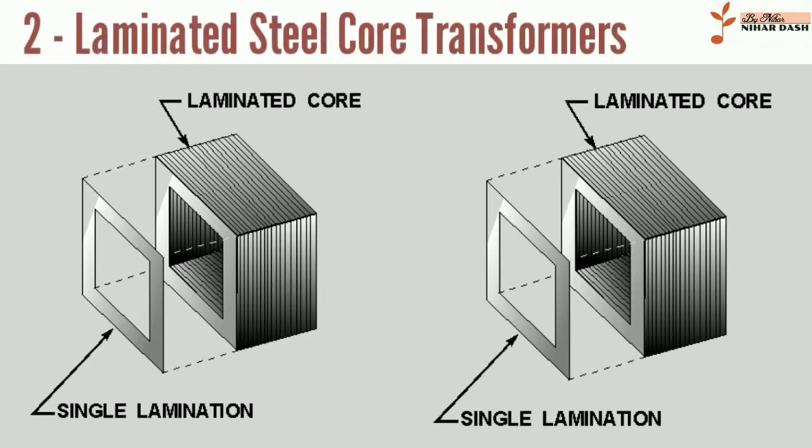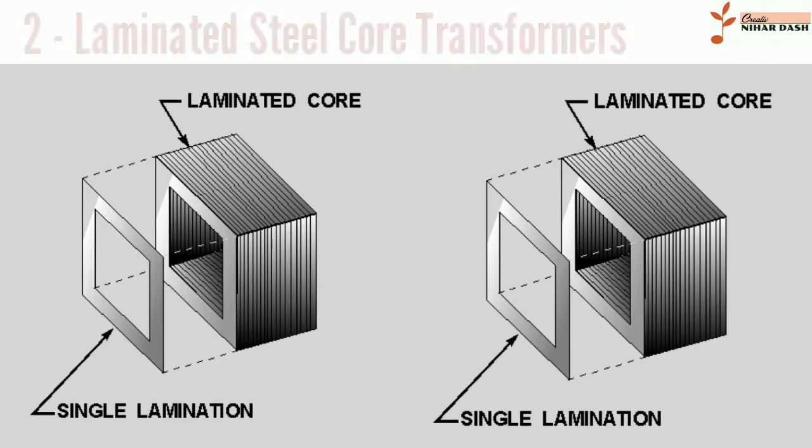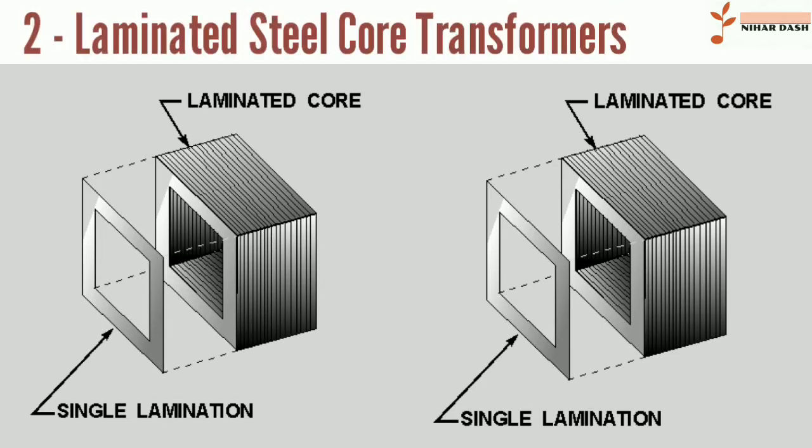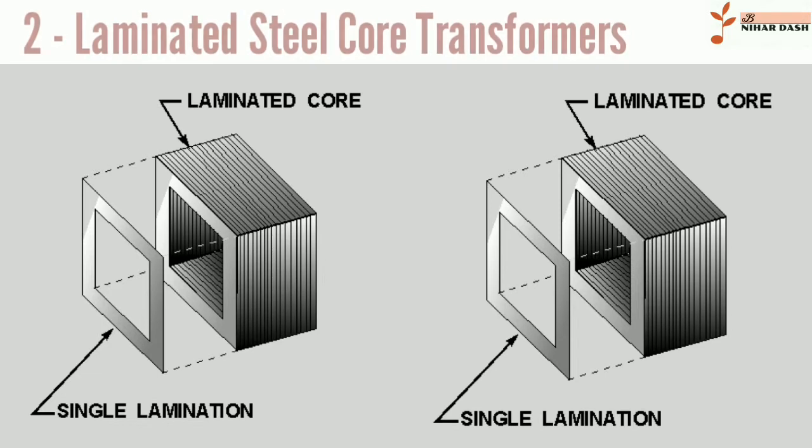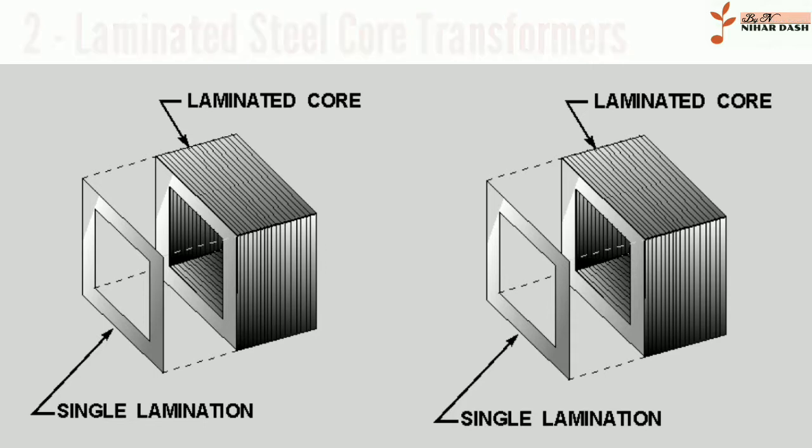One common design of laminated core is made from interleaved stacks of E-shaped steel sheets capped with I-shaped pieces, leading to its name of EI transformer. Such a design tends to exhibit more losses, but is very economical to manufacture. The cut core or C-core type is made by winding a steel strip around a rectangular form and then bonding the layers together.